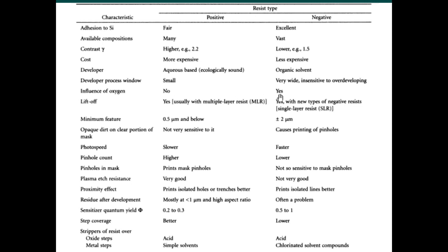Also in terms of process windows, with negative photoresist, you have to be a little bit careful about oxygen and humidity. So one of the reasons why the clean room has very controlled humidity and temperature conditions is because these photoresists are quite sensitive to different environmental conditions. Okay. The humidity has to be controlled. The temperature should be controlled properly. I've heard of horror stories when grad students at one university are not able to repeat the experiments at other universities because the humidity was a little bit different in one clean room versus the other. So a lot of these processes do have to be optimized properly.